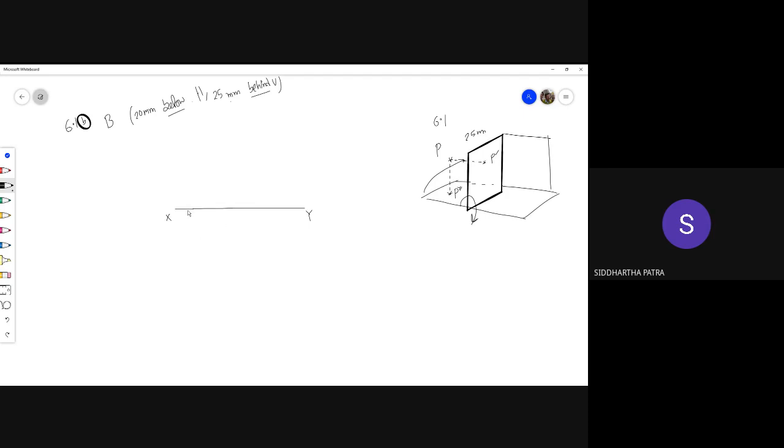Now you'll have to imagine the horizontal line after being rotated, the negative side of the horizontal line that actually extends into this portion, this region. Okay, so imagine this is a simple vertical line crossing the xy line or intersecting with the xy line. On that, we would draw p double prime, which is the horizontal projection.